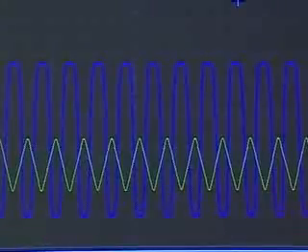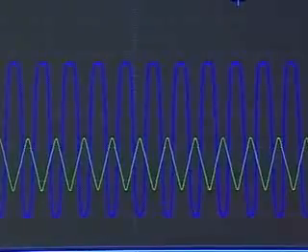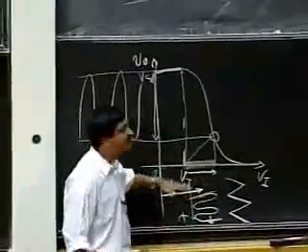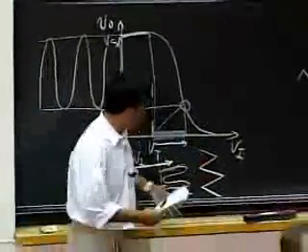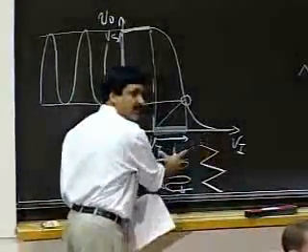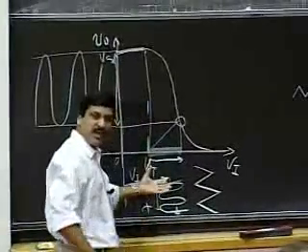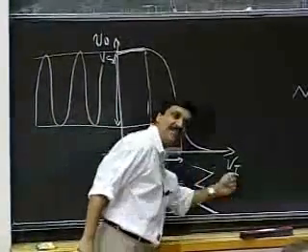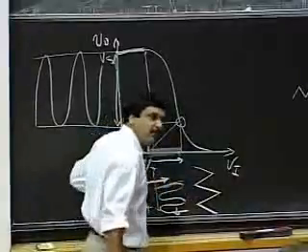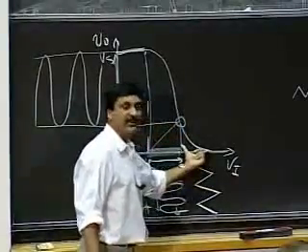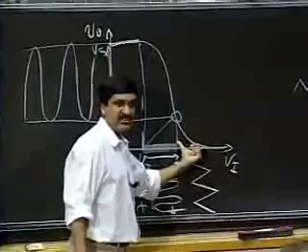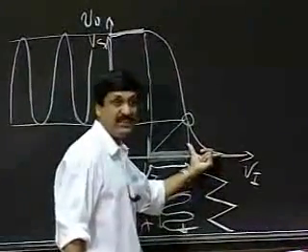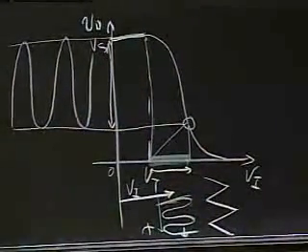Now let me apply way too much offset. With this offset, I'm kind of operating here. What I'll do now is apply an even higher offset so that this triangular wave begins to move here. If I apply a very high offset, what I'm doing is overdriving the amplifier, boosting it so high that the MOSFET is going to go into its triode region, and you're going to see that I won't have any gain. My output is going to shrink noticeably if I overdrive the input.